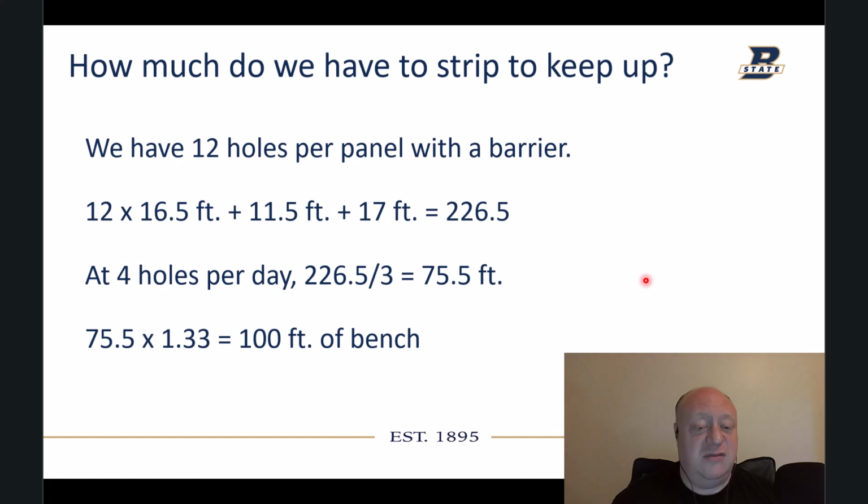That's to allow you to have space to observe how the highwall is behaving. In fact, it's even better to have more space than that if you can, right? But you do have to balance that with your reclamation plan and where you have to store your material, how far you're hauling. You have to balance those things.